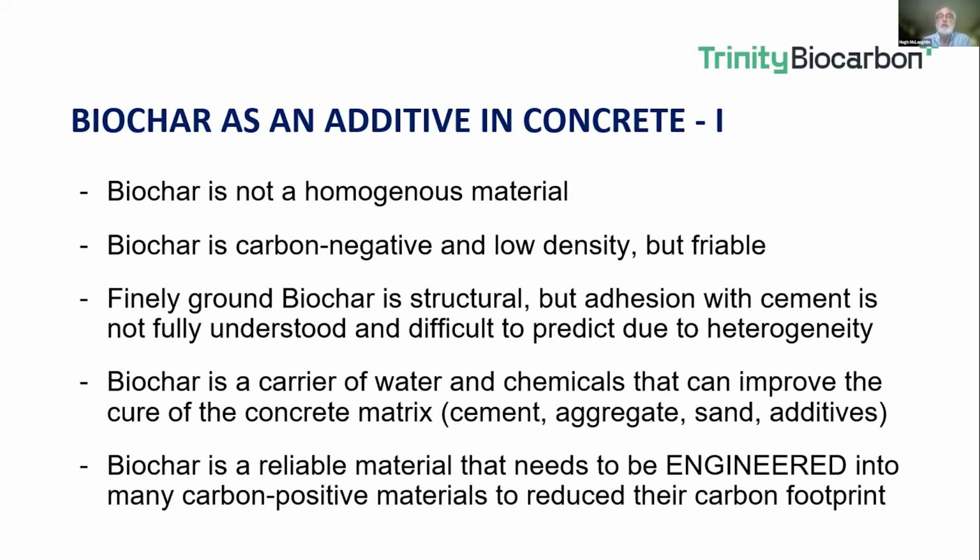It is undeniably carbon negative. It is low density. That is helpful in concrete because as you build up, weight becomes very expensive, and therefore lowering the density of the concrete is helpful. But it is quite friable, which means it crushes, it breaks down. Think potato chips. Potato chips are friable, and that's why the bottom of the bag ends up with little potato chips. But if you grind it to a small scale, it actually becomes very structural. It becomes carbon nanotubes, and that is a very strong material. Then the issue of binding all these particles to the cement needs to be guaranteed or worked out, and that's an area of research.